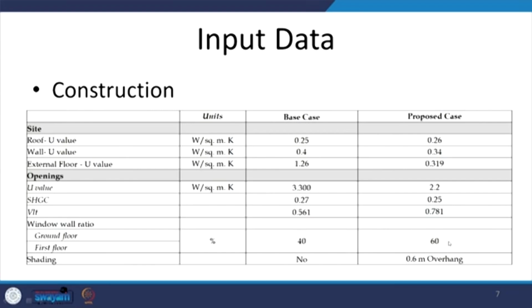So, though this is a negative thing as per ECBC prescriptions for the climate of Delhi, window wall ratio approximately 40% is the best proposed one. However, if we increase the WWR to 60%, but also improve upon the type of glass, let us see what kind of differences in performance do we see.